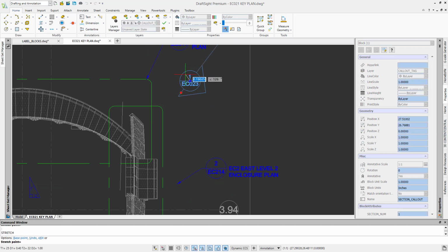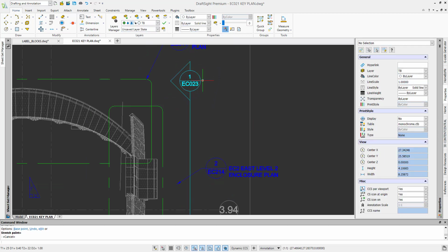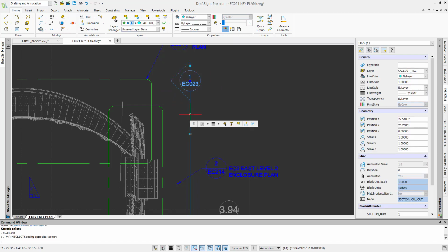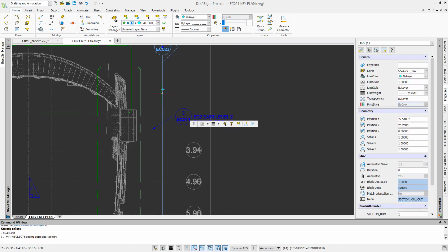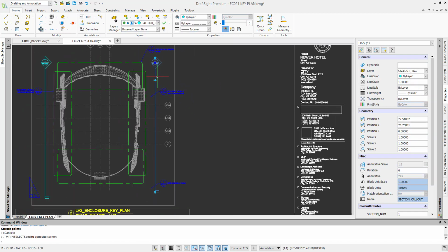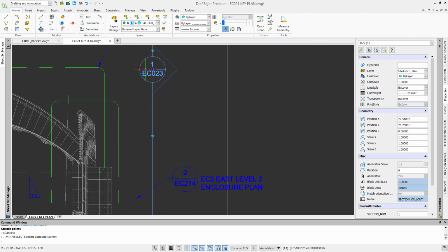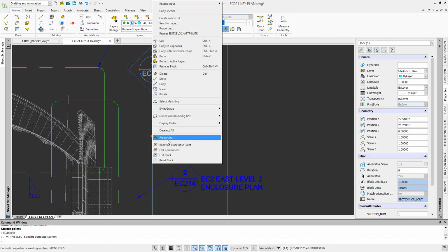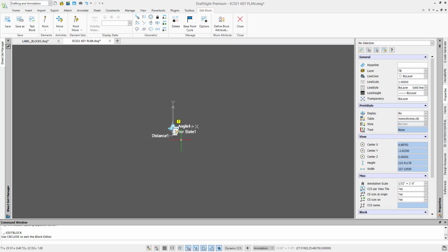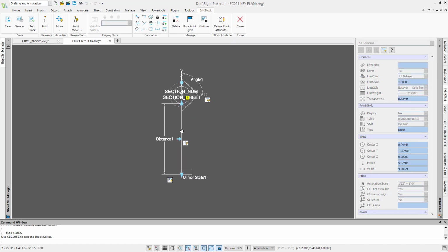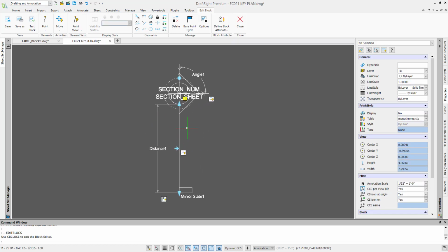So you're actually rotating it to represent what you actually want represented. And then last, there's also a mirror element here, so it mirrors both sides. Again, keeping the text kind of oriented correctly upright the whole time. So this is just a little bit more of an advanced example of what you can kind of do with these custom blocks in terms of creating callout blocks.